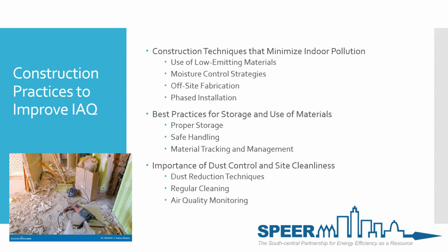And then safe handling is ensuring proper ventilation when using high VOC products, and following manufacturer guidelines for that use. And the material tracking and management. That's become a bigger and bigger thing when you look at above code programs and higher indoor quality certifications: keeping a record with the inventory of those materials, and tracking where they've been and what they've been subject to. Because we all know wood absorbs moisture, but if it's been around a contaminated job site, it can also absorb some of that moisture that's laden with pollutants that now will off gas over time.